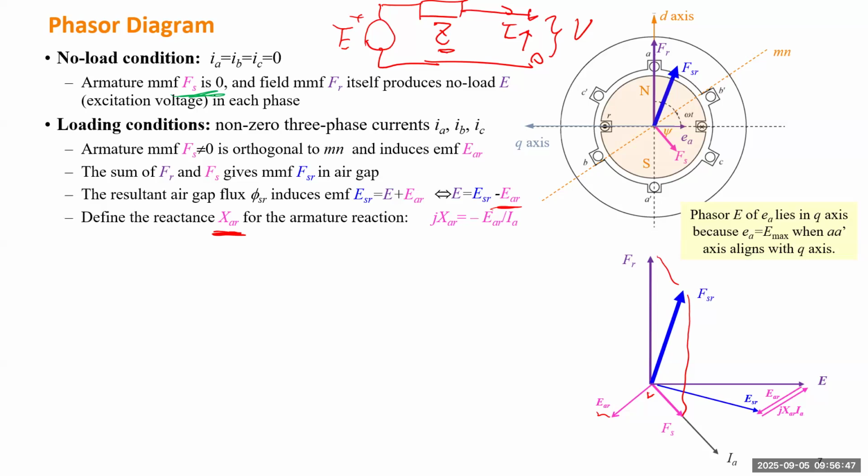So if inside the generator there's some reactance, this Z will be contributed by some reactance. That reactance carrying the current will create a voltage drop. So that explains why the terminal voltage of the generator can be smaller than the internal voltage. And further, you can also add the resistance and some leakage reactance. For a perfectly designed generator, that one can be ignored. But when there's an air gap, some flux linkage is not contributing to those voltages and will be lost. So you can also add that part.